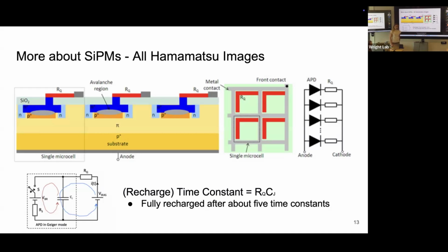So I used a blue laser, like a laser diode. Is that what you used, a laser? It was a light source, it was an LED. Okay, yeah, so a laser is monochromatic, just one wavelength being outputted. So that was kind of an arbitrary choice. 405 is a cheap laser that we can get with a roughly Gaussian beam. The green laser, sorry, is what we just had lying around and what I could commission the setup with. And a SiPM is blue light sensitive, so it's preferable to work with blue light. So that was another reason to choose the purplish 405 nanometer.